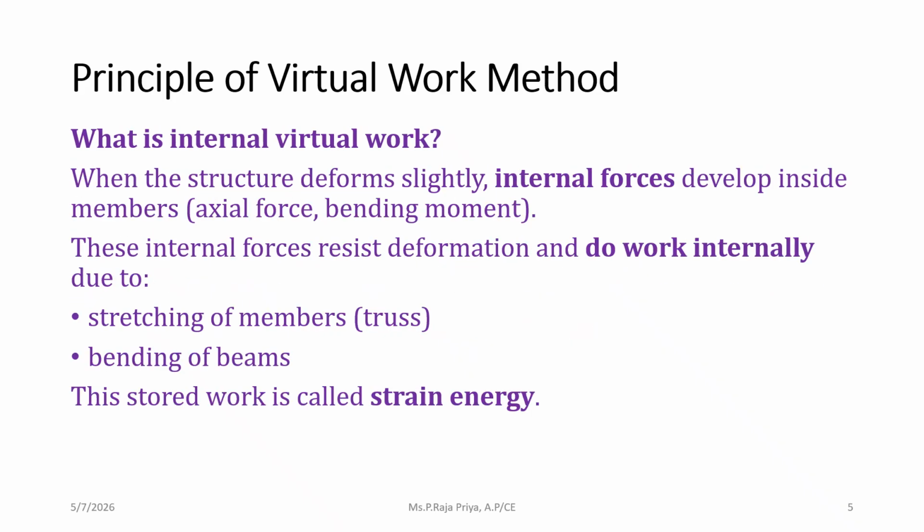And next, what is internal virtual work? When a body or a structure is subjected to any kind of deformation, some internal forces will be developed inside the member. These internal forces will try to resist the deformation and they will do the work internally.